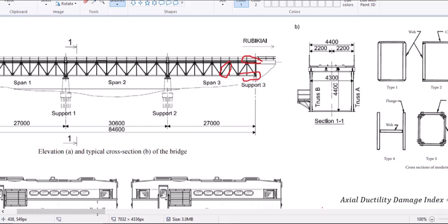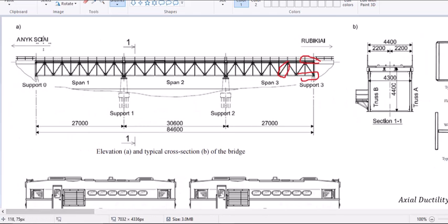And in the third analysis we are going to have a movable displacement, so we are going to change the displacement from this point until this point, and then this point to this point, and also changing the movable displacement from this to this, and then running the pushover analysis in the vertical direction and seeing the result.